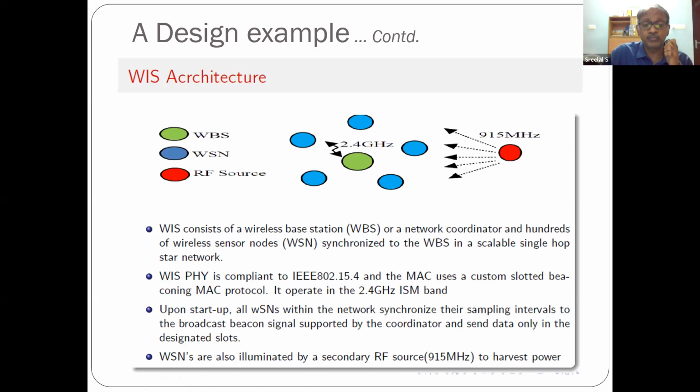So what are the advantages of this? Basically, data communication is done by wireless means. That is the advantage. And in a launch vehicle or in a spacecraft, when we do this, we are able to eliminate the wires. The wires constitute quite a lot of weight in the payload bay of the launch vehicle as well as in spacecrafts. And therefore, by eliminating wires, we are able to reduce a lot of harness weight. So that is the basic advantage of this wireless instrumentation technology when we adopt it in spacecrafts as well as in launch vehicle.